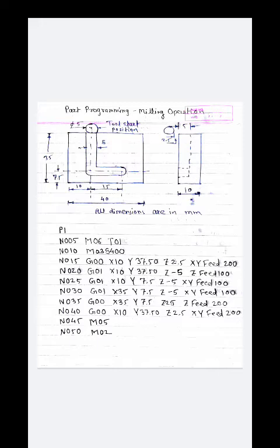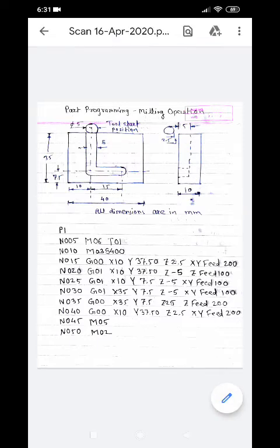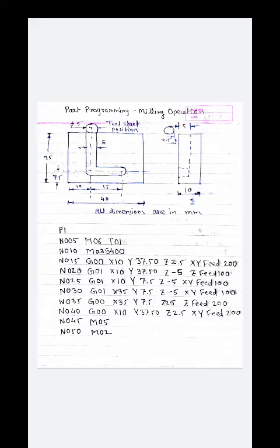Here I have taken a 5 mm depth of cut directly. We will see later what happens if we take 1 mm. So our cutter is moved in the downward direction, and here the feed starts.